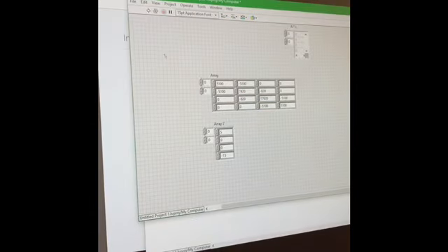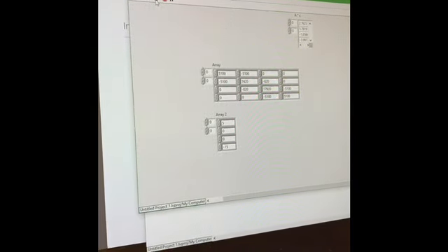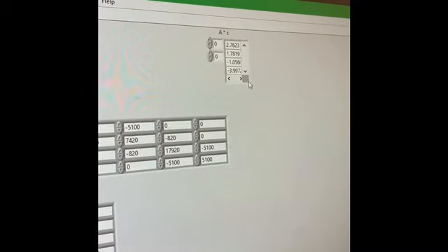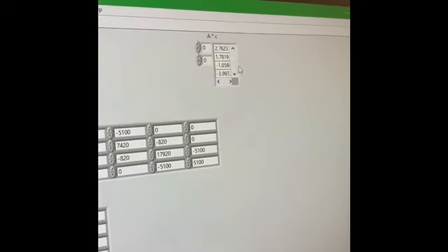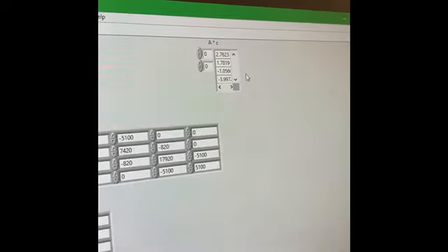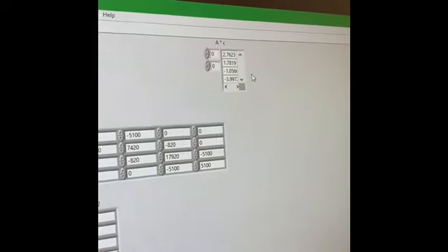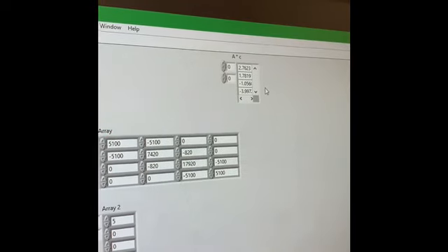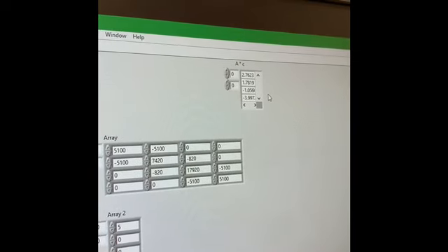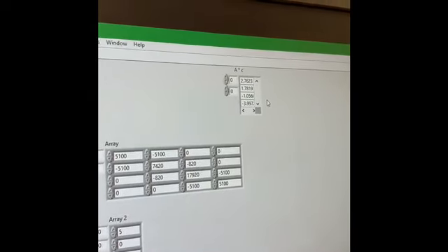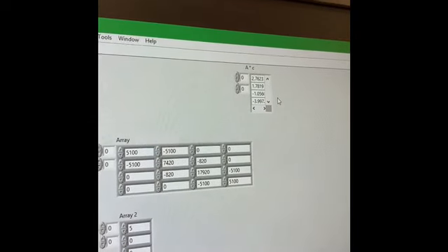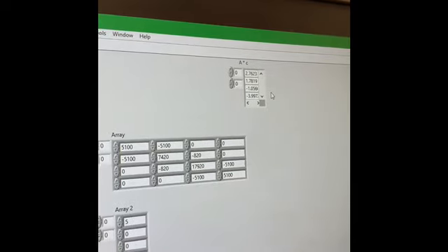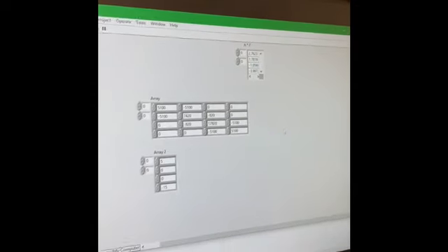Alright, so now you can run your program. And from there, you'll see the values of your I1, I2, I3, and I4 outputted. These also match the values we got from measuring during the circuit. We measured 2.66 milliamps for I1, 1.70 milliamps for I2, negative 1.08 milliamps for I3, and negative 4.03 milliamps for I4. So we can see that they're pretty similar and almost the same.